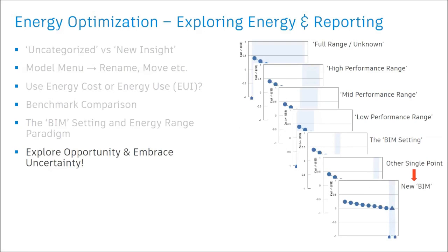And the point is, this whole range of factors really allows you very quickly, from a single model, to understand design opportunity, like the role of passive design, whether it be orientation or glazing, shading, or whether it be more system side levels of efficiency, envelope properties and so on.